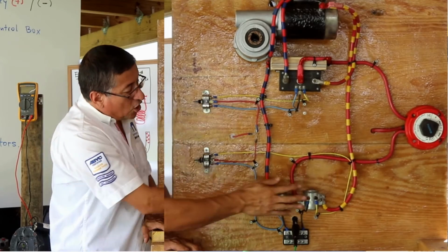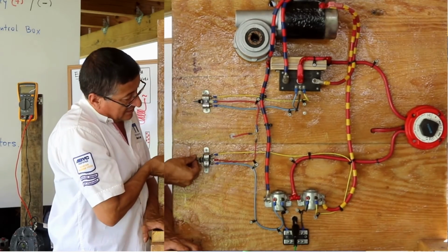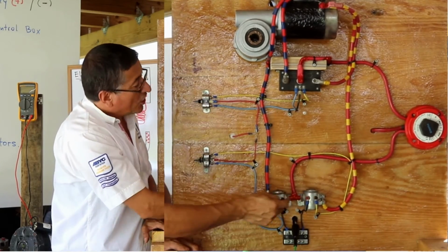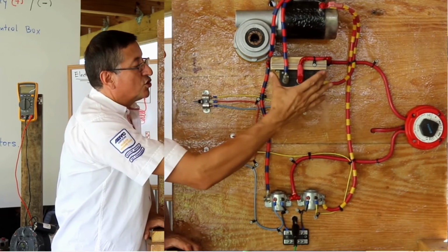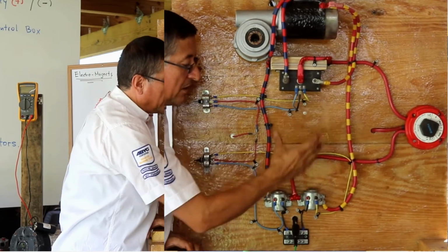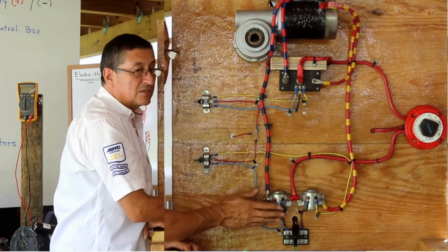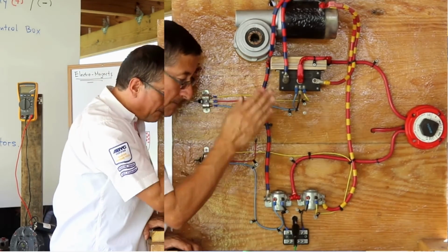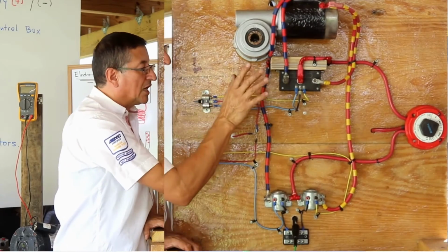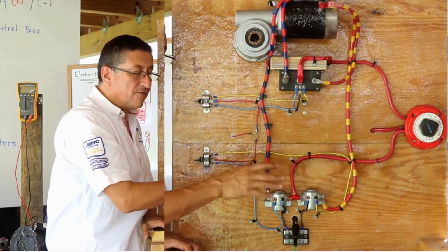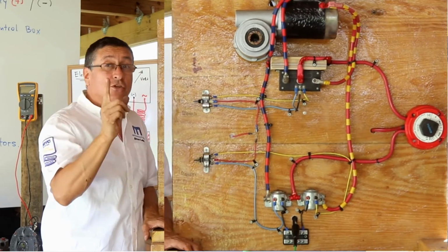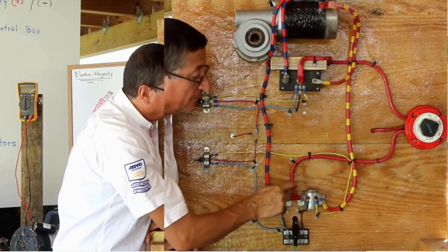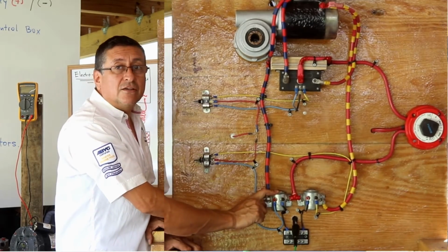This is the switch to operate those relays, and it works exactly the same as the solenoid control box. You replace that expensive equipment with $20 for this situation, and this is a permanent good solution. You can replace this with this forever. You don't have any problem, you don't have any inconvenience. The only thing that you need to verify is the capacity in amps of the relays.